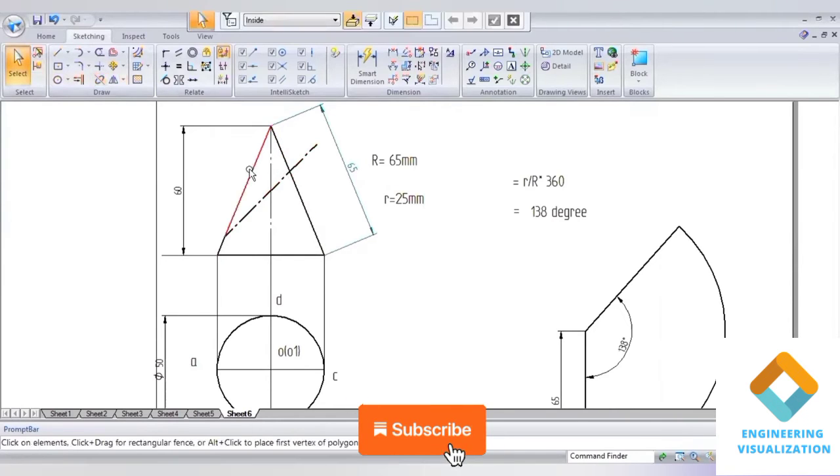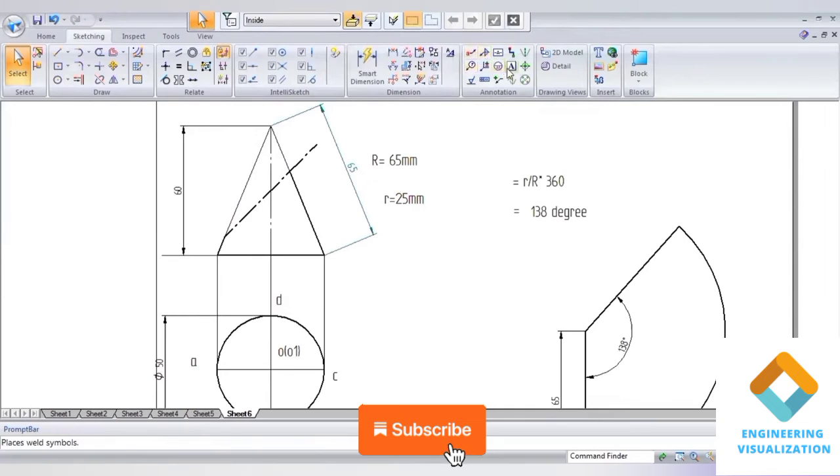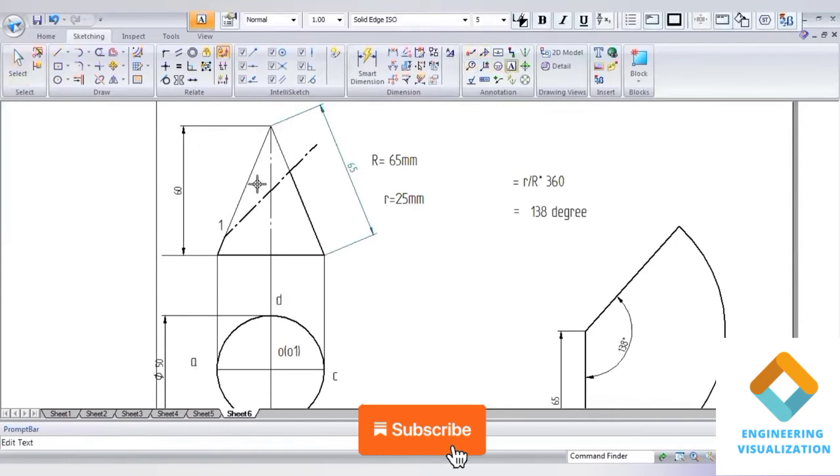Okay, make those lines as thin lines, 0.13. Okay, we can mention 1, 2, 3 here, but we should project these 1, 2, 3 points. Okay, 1, 2, 3, 4 points on the slanted length. We have the slanted length of 65 here.